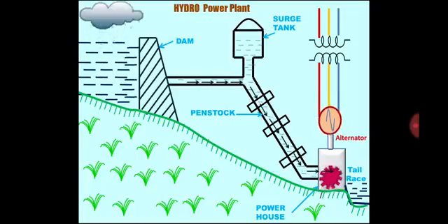And at the start of that penstock there is a surge tank. Now what is the purpose of that surge tank? If for maintenance purposes the powerhouse is closed, the intake to the powerhouse will get closed, the gates will get closed. So a heavy amount of water will get stored in the penstock. The pressure inside the penstock may increase, and the penstock may burst. To save this, the surge water can go to the surge tank. Basically the surge tank is used for that, and acts as protection for the penstock.